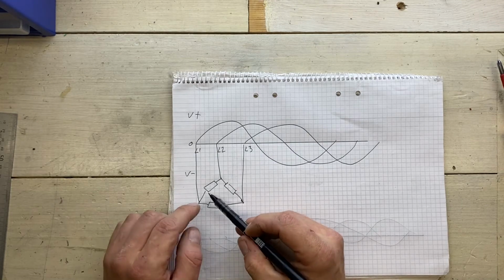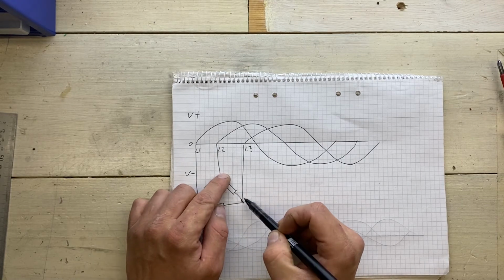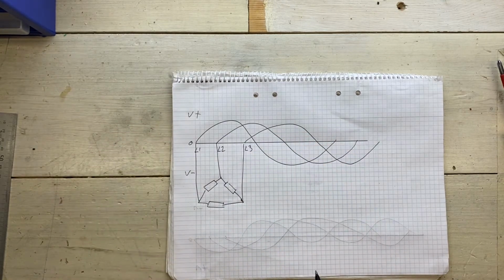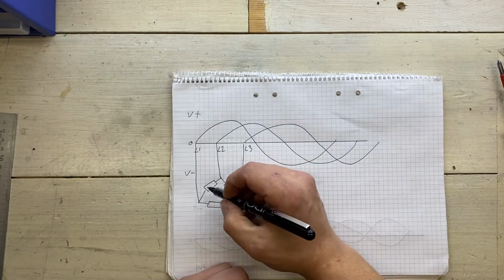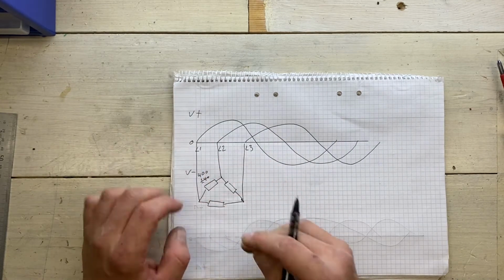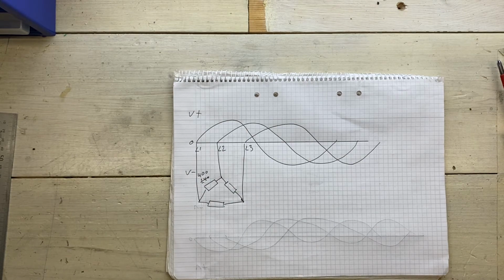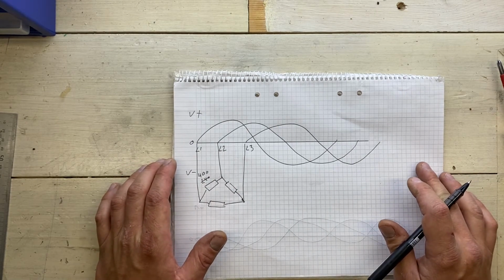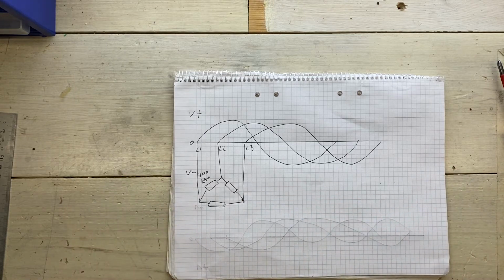And that means that across each of the windings, we have the voltage that is between 2 phases. And here in Europe, it should be 400 volt AC. Now some countries, like Norway, have a 240 volt 3-phase system, but here in Sweden we have 400 volt.